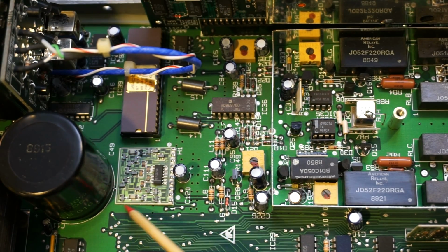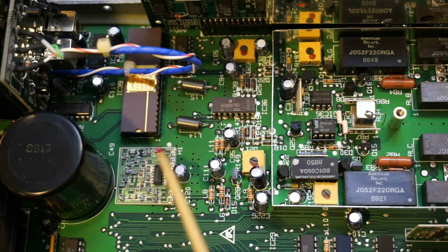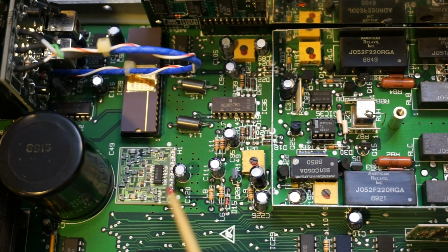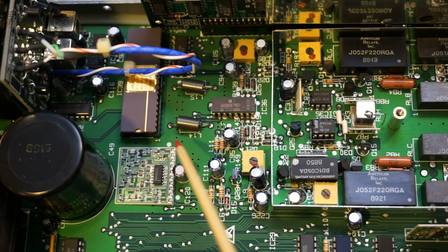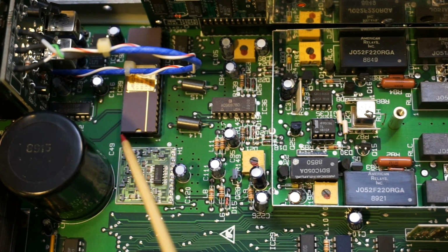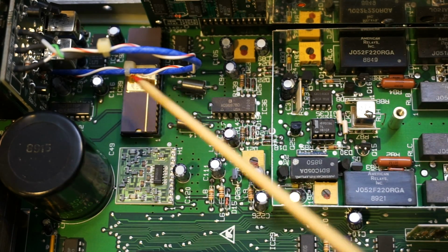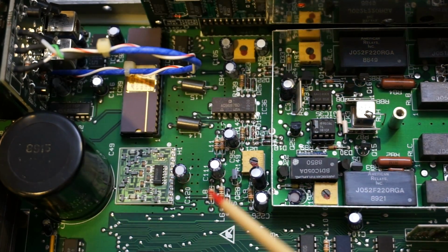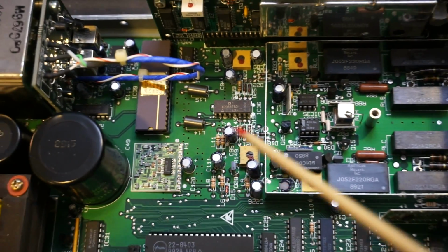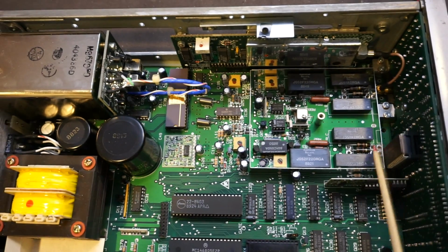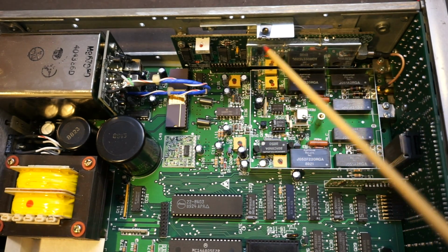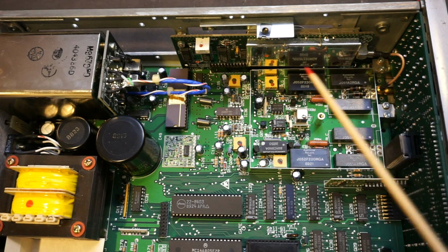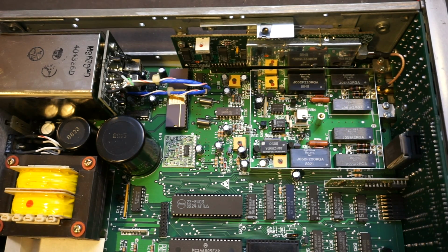And as you can see, this differential amplifier is actually a separate circuit board. I suspect they make it that way to make sure that this portion of the spec is tightly controlled. And then afterwards we go to some custom circuitry, basically controlling the gate and the timing; the display is back here. So pretty much everything is exactly how a frequency counter typically works, as I explained before. And so that's about it at a very high level.